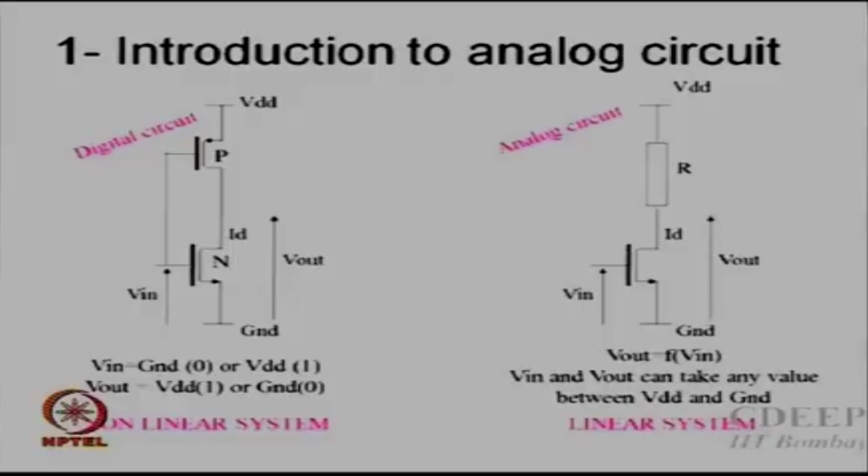So it drives. In the CMOS case, one cannot say N channel is a driver because the other signal is also connected to P, whereas in this case, this transistor is a driver. In an NMOS inverter, yes, there will be a driver transistor and a load. This is like an NMOS inverter as well.